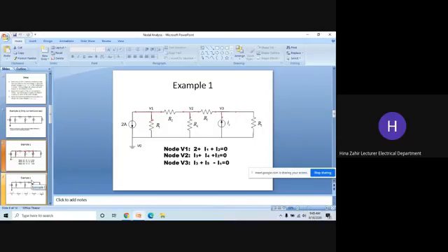We know what Ohm's law is. V is equal to IR, and if you want to find the value of I by Ohm's law, I is equal to V by R. Voltage divided by resistance is equal to current I. So what we are going to do is replace these currents I1, I2 with V by R, which is okay. But how? Now look at I1. It is this current which is going through R1. So what are you going to write? V1 by R1.